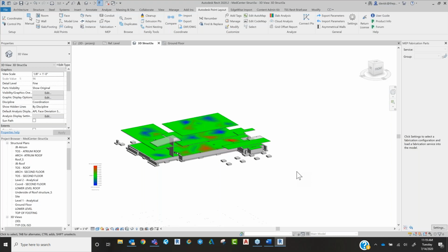Yes, sir. There's a couple different ways that we can do that. I don't have the Glue plugin installed, but typically you would download the Glue plugin, BIM360 Glue, and from there you can create views that you would push up into BIM360 for layout. You'd place all your points, so it's the same kind of thing. You're going to Glue, pushing the shared view up into the cloud. And then as you make changes, you can update that model in the cloud, and anyone who is granted access to it can then access it, okay? And they have all the information there.